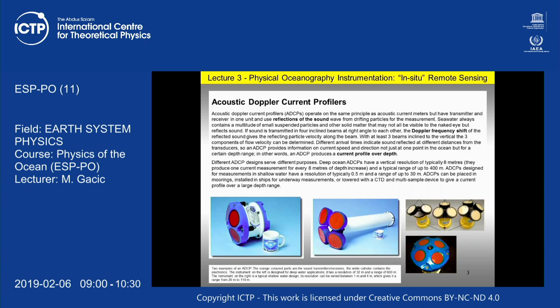You reconstruct the flow pattern. You calculate the flow rate, and you obtain also how the current is distributed. And this is where, you remember I showed you the profile, the vertical transect of the flow, and we obtained that there is an inflow here in the Adriatic, and here is the outflow from the Adriatic. And this has been obtained from these kind of ADCP measurements.